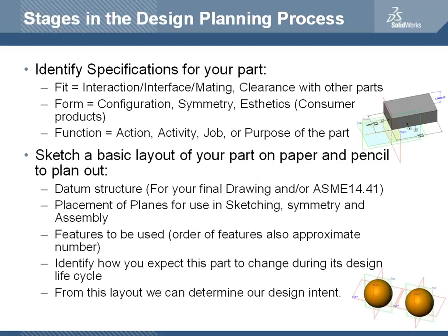The second stage here is to sketch out a basic layout of our part on paper and pencil. This will allow us to plan out the following: our datum structure. This will be used in the final drawing, or if your company has adopted ASME Y14.41, that is the standard by which we can utilize a 3D model in place of a drawing, so long as that 3D model contains all the information that would otherwise be present on your drawing.